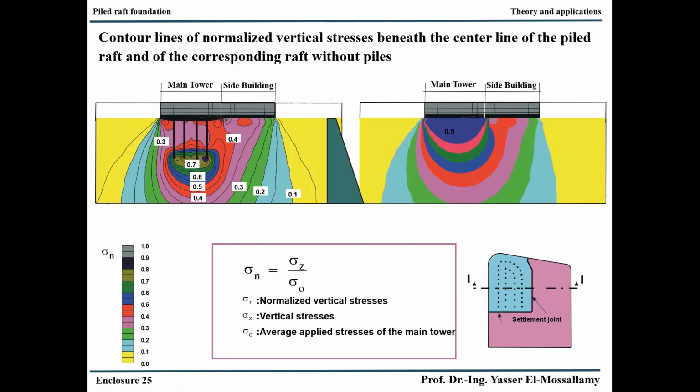We should also consider that in all these cases we speak about floating piles. That means the piles are in the clay layer. They don't penetrate completely the clay layer and come into other stiffer soil, but they completely end in the same compressible layer.